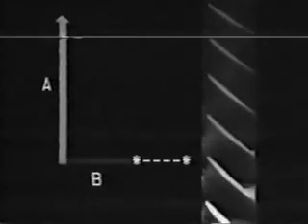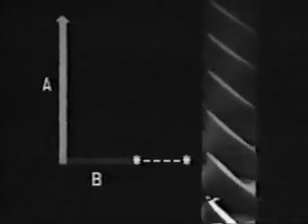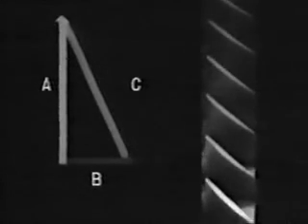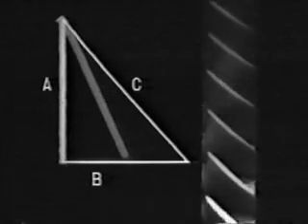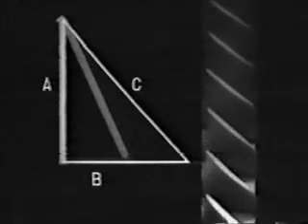But while the forward stages are pushing air, the rear stages aren't able to move it on rapidly. Here's the result. Vector A is now the direction and speed of the rotor blade. But the airflow has slowed down due to blockage in the rear stages. Here's vector B again, with its velocity component shorter than before, representing a drop in airflow speed. Here's the resulting relative speed and direction of airflow on the blades. Vector C meets the airfoil at an increased angle because air velocity has been reduced to half.